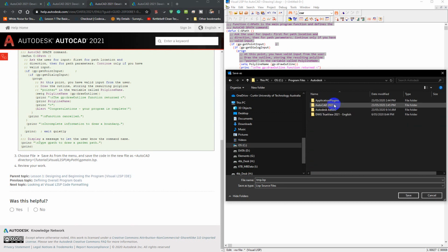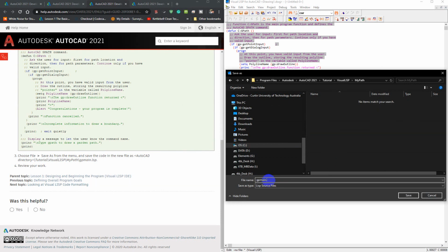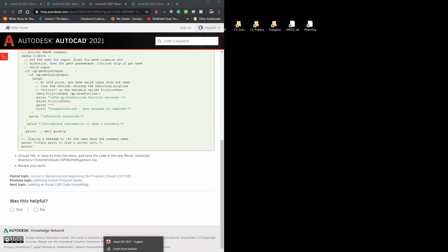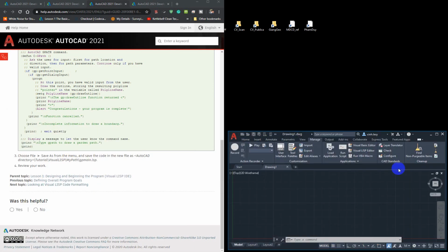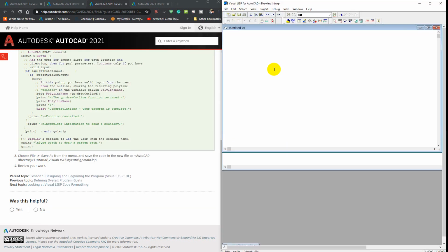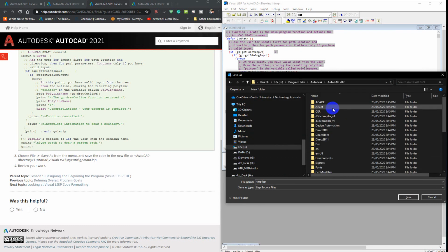In the Visual Lisp window, the mouse pointer appears as a Visual Lisp symbol, and you cannot choose any commands or enter text anywhere in the Visual Lisp window. The pointer symbol is a reminder that there is an activity you must complete in AutoCAD before resuming work with Visual Lisp. Remember this whenever you see the Visual Lisp pointer. We can see that. Now you are ready to begin building the garden path application.